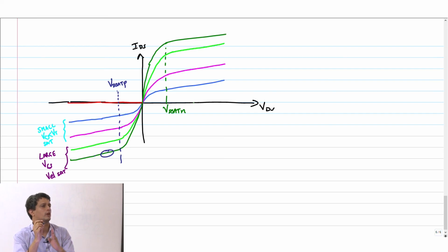It doesn't increase any further, which depends on your VGS value also. If it saturates earlier, then that will basically dominate and you will get a saturation current. Otherwise, you will get a velocity saturated current. Clear? Not convinced? That is VDSAT, the velocity saturated drain source voltage, the drain source voltage at which the current becomes velocity saturated.